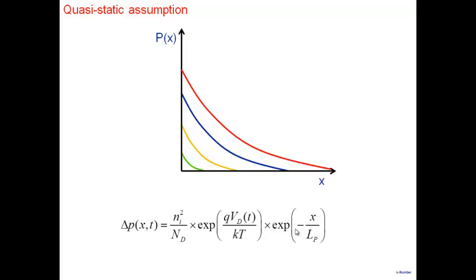But the meaning of capacitance is transient. So how can I do that? You're seeing there's a problem here. To get capacitance, C is ∂Q/∂V. I need Q, and Q is the integral of qp dx. How do I get p? I'm using p from the static variation, substituting and calculating an expression for capacitance. And capacitance is used only under transient conditions. It has no meaning in static. So that's the problem.